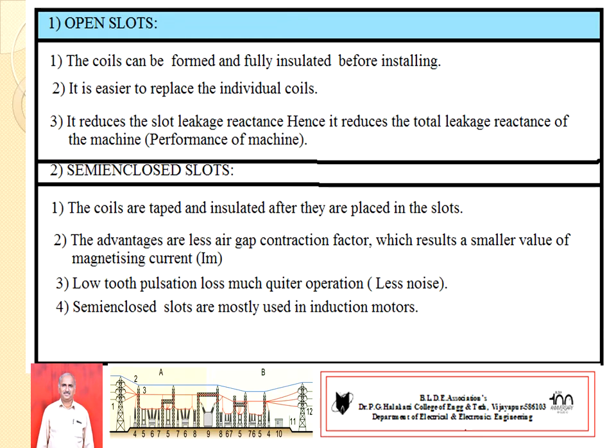Then it also provides low tooth pulsation loss and less noise. It is also another important parameter for industry. If motors operate with less noise, these are a more preferred selection. Hence almost all types of induction motors are designed with semi-enclosed type slots.